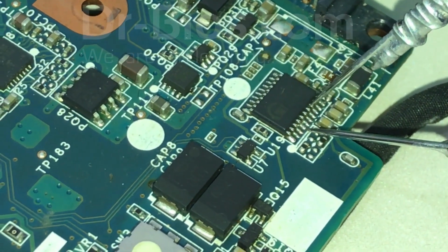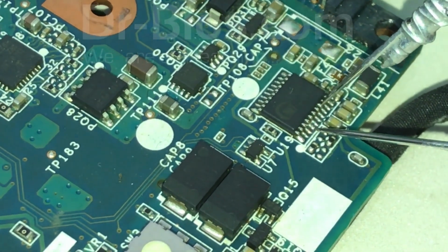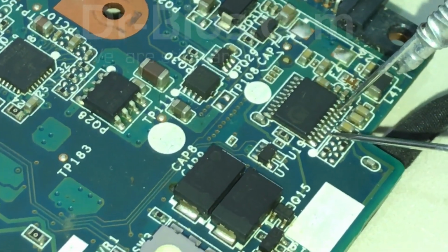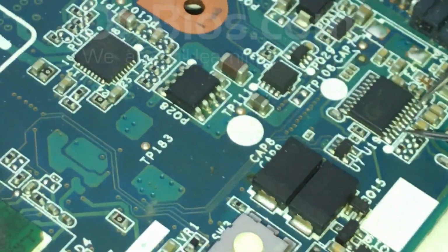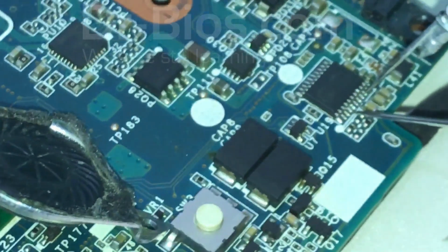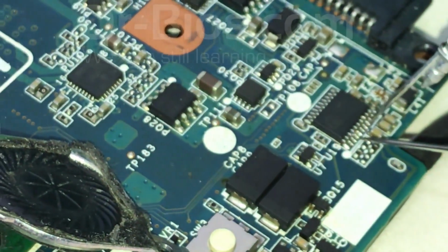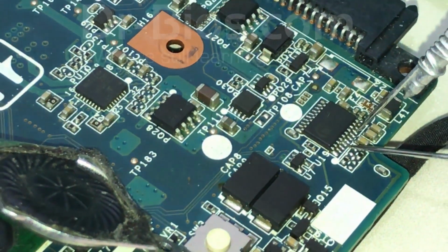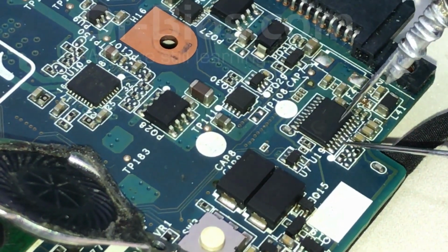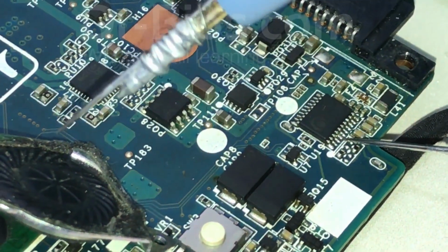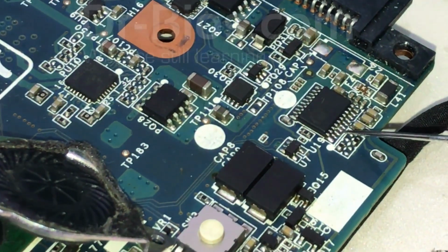You can hear the weird sound of the speaker. I place the probe on pin 4 and connect and disconnect on pin 8. Noise sound of the speaker means that the direction of the amplifier output to the left speaker is okay.